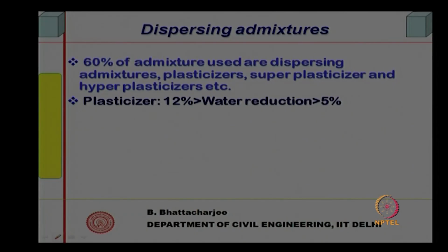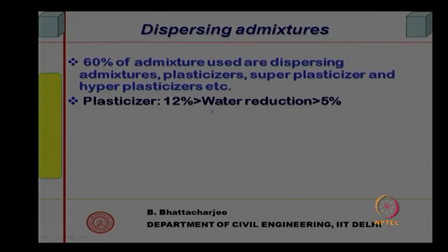As we said, that came pretty early, and this can reduce water. They plasticize the concrete, so they essentially reduce the water demand in concrete. You can make it plastic with less water, that is the idea. If you add them into the concrete, they will make it more plastic, more flowable. Therefore, for the same plasticity you can reduce the water required.